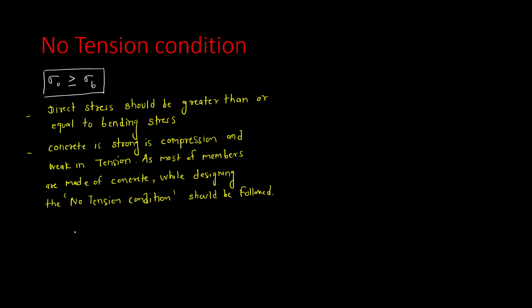So we should follow the no tension condition. If we do not follow, then what will happen? That means if tension develops in a concrete member, then tensile cracks will develop.